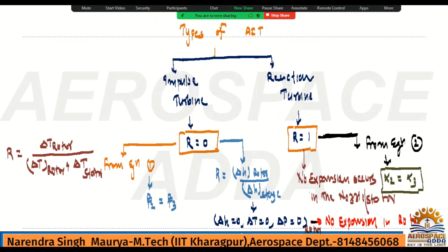Okay, so in this very small one slide I have explained all the concept behind the impulse turbine and reaction turbine. What are the variations of the components? I mean, components in the sense angle-wise, and rotor and stator contribution, all those things are explained nicely here, in short. Now the most desired degree of reaction is what? 50%, as I told you. So that I will explain separately.